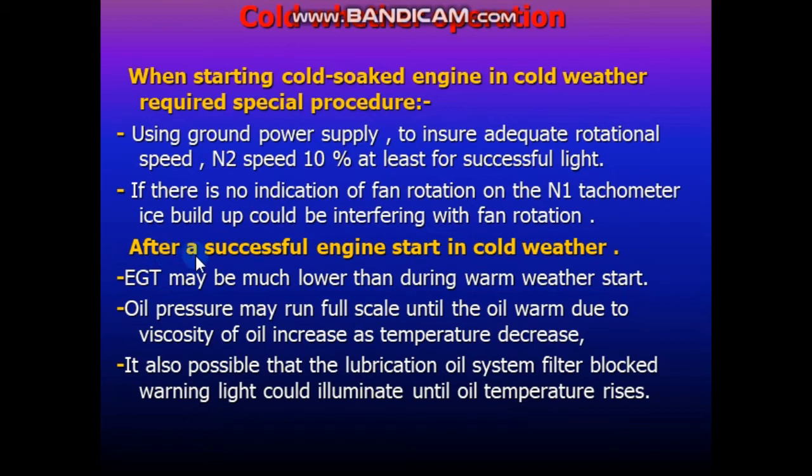After successful engine start in cold weather, after you start the engine and everything is good, the EGT may be much lower than during a warm weather start. When you focus on or monitor the EGT, you will find that it will rise, not like the warm weather.